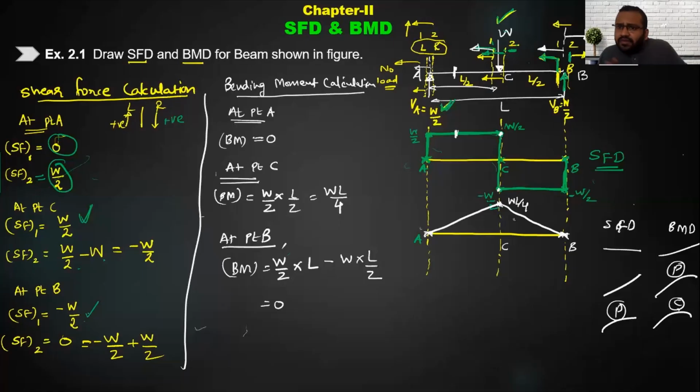Yes, sir. Yes, it will not fail. Why to take for W? So shear force diagram enables us to know what is the maximum value of shear load or what is the maximum value of bending moment my material will be subjected to. And I will take only up to that value. Why to take for maximum loading? Unnecessarily I am using extra material, it will increase my cost.